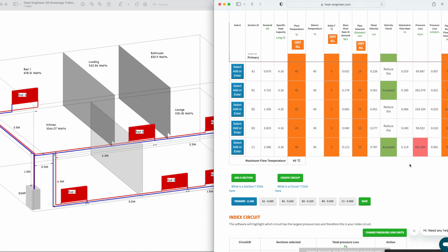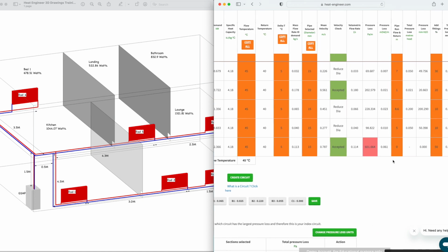Yeah, it is, but I'm going to carry on, because we've got residual head. You know, the standard states between 300 and 500 pascals. We're 100 pascals over. So yes, it is higher and it's outside of our design parameter, but that might be existing. It might even be buried in the wall or whatever. You don't know. This could make or break you winning or losing a job if you've got to replace all of this pipe work down here. And sometimes you will not have to.